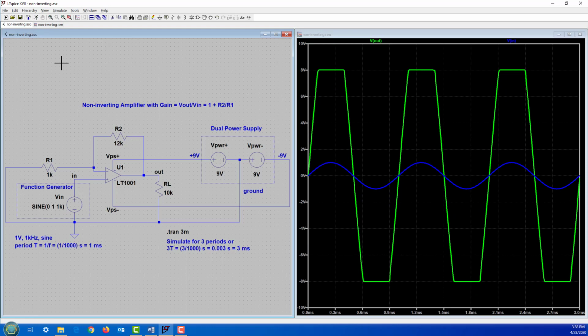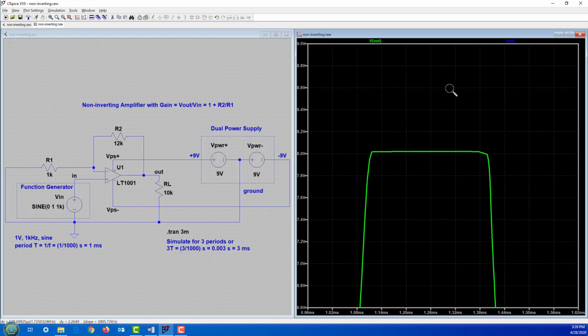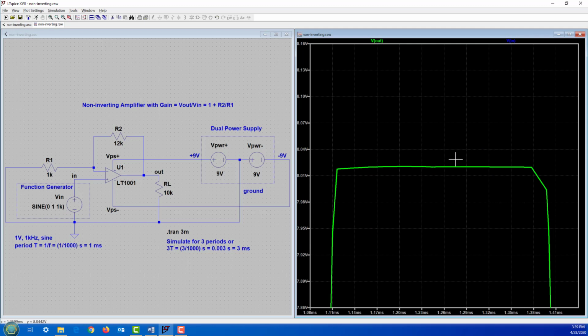So you got clipped, is what happened. What's that clipping voltage, right? What's that maximum? Looks to be about 8, and then down to minus 8. Okay, you want a better idea? Well, you go on the waveform, right? You click on the waveform window, you highlight it, and then when the cursor turns into a cross, left click and choose the rectangular area, and then let go, and then you can zoom in more and more and more like this.